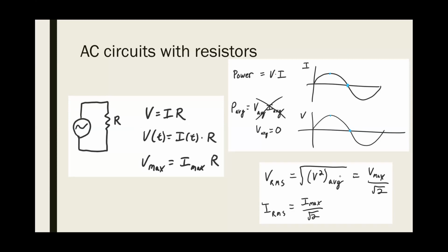If I want to find the power, I can't just take a simple average, which will always give me 0. That won't really reflect the situation. So we develop the RMS, where we square the function, then we take the average, then we take the square root. If we have a perfect clean cosine function or sine function, this works out really nicely. It just gives us the amplitude divided by root 2. So that's a fairly simple way to switch back and forth.